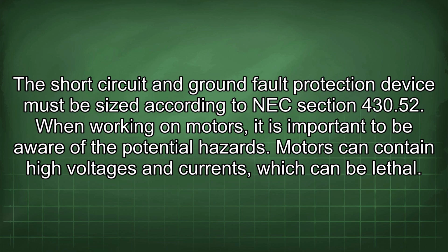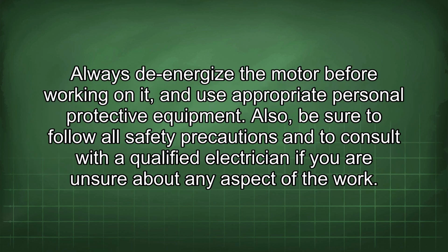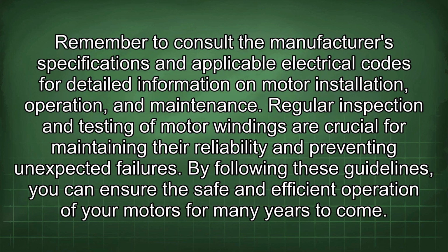When working on motors, it is important to be aware of the potential hazards. Motors can contain high voltages and currents, which can be lethal. Always de-energize the motor before working on it and use appropriate personal protective equipment. Also, be sure to follow all safety precautions and consult with a qualified electrician if you are unsure about any aspect of the work. Remember to consult the manufacturer's specifications and applicable electrical codes for detailed information on motor installation, operation, and maintenance.